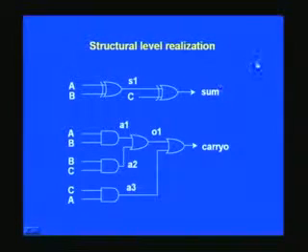And the very same full adder depicted using gates is this, and with an eye to primitive gate implementation, it has been put in this fashion. Note that S1 is an intermediate signal which we will be using, and similarly A1 through A3 are intermediate ANDed operations here. You can OR these, and once again O1 is an intermediate signal we will be using, and the final results are sum and carry.